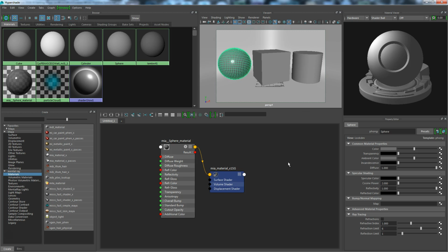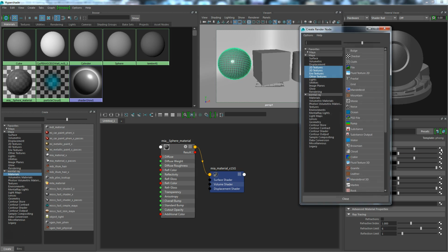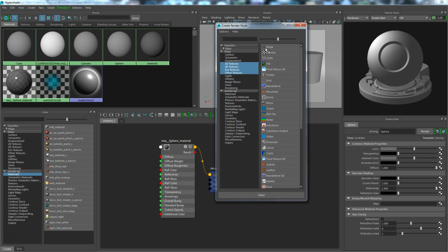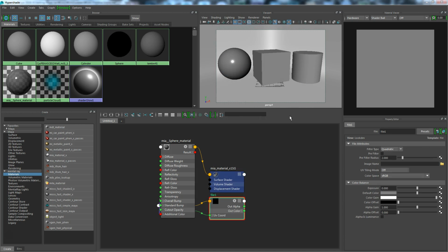Okay. Now, with its attributes over here in the color, that's where we're going to load our little checker pattern in. So you want to click this little box over here on the side, and we're replacing the color with a checker box. Okay. Now they have a checker procedural texture in here. It's a 2-dimensional procedural texture that you can use, and that's fine. But we're going to use this file that I gave you. Okay. So I'm going to click on that.